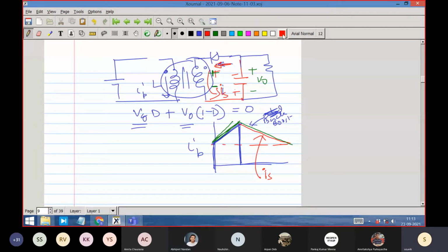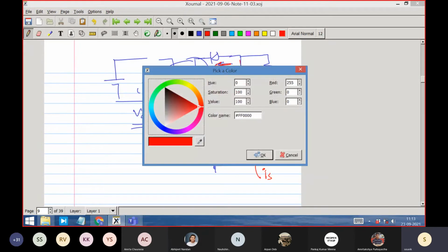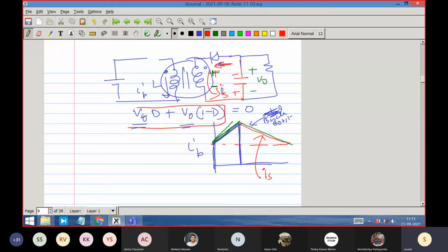The actual voltage here is what? Volt second balance. The actual volt second balance is suggesting what? For a common Vg, V0 is negative. So that means the true polarity of this is minus plus. However, the inductor forces the diode: this current must flow. It doesn't depend on this voltage. Whatever may be the voltage here, it will still conduct, like even in a buck converter. How does it then conduct? You will see, let us say, a buck converter.